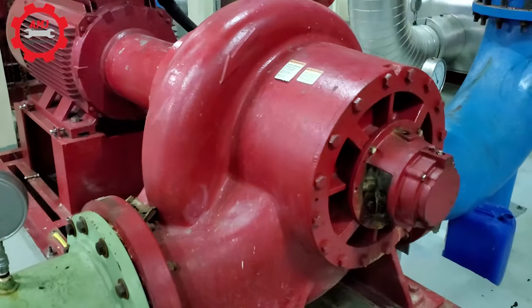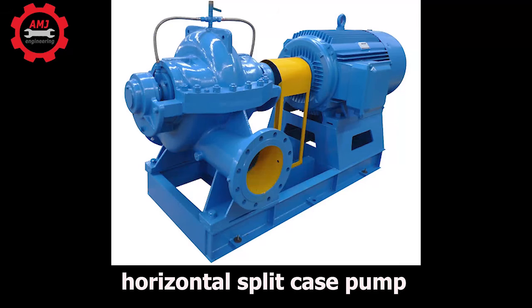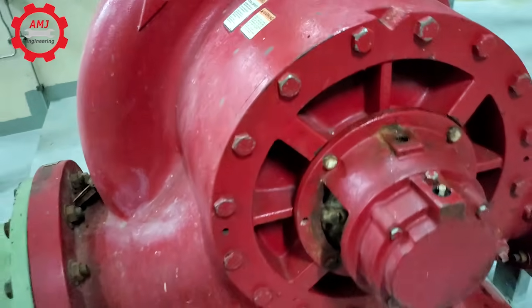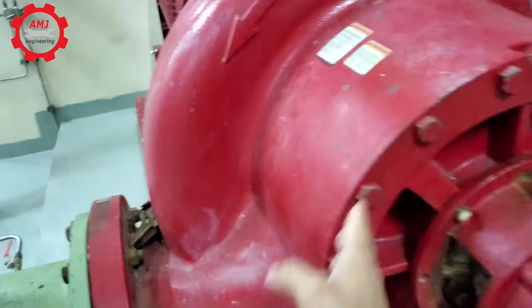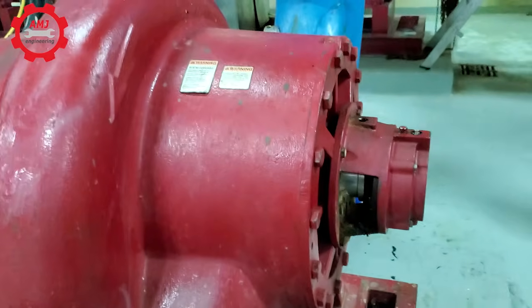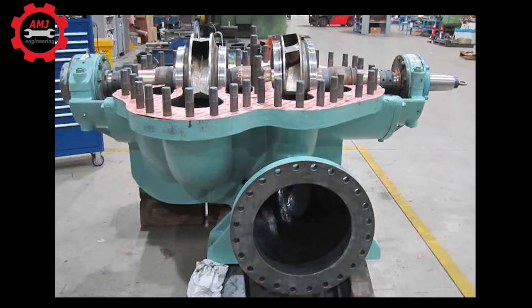Split-case pumps are available as horizontal or vertical split-case. For horizontal split-case pumps, the impeller casing is usually split in the horizontal plane. For vertical split-case pumps, the impeller casing is split in the vertical plane. To have the casing split is an added value to the pump because it allows full access to the impeller for maintenance.